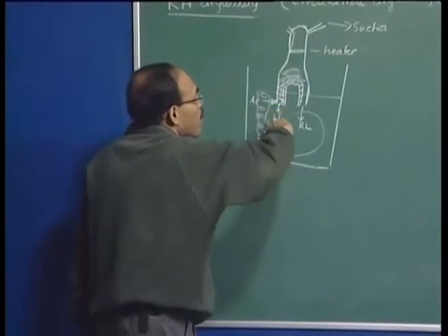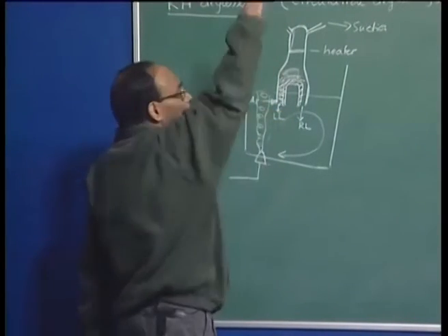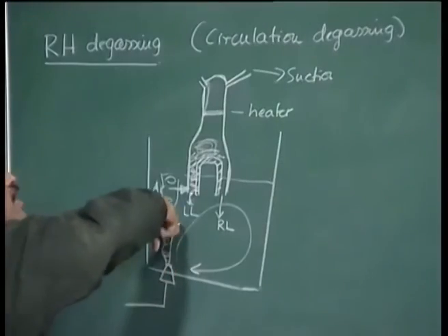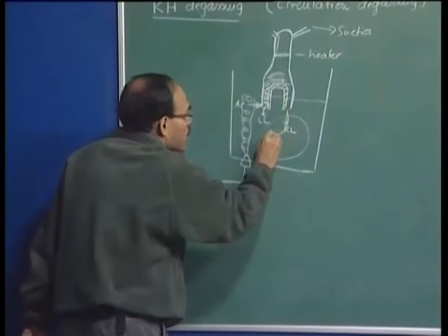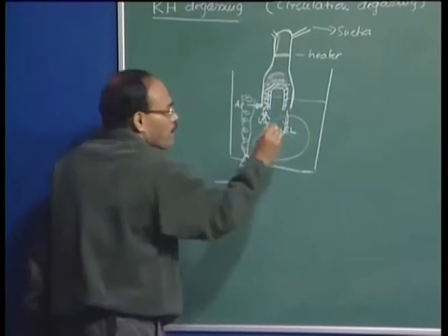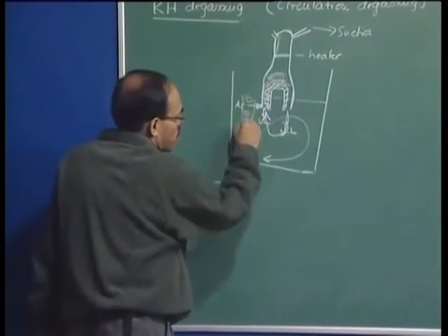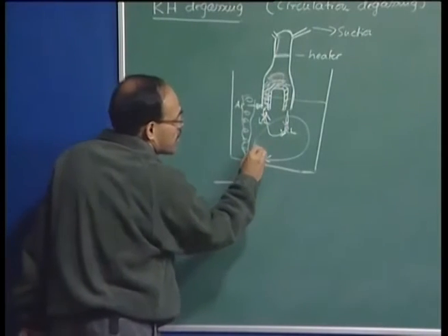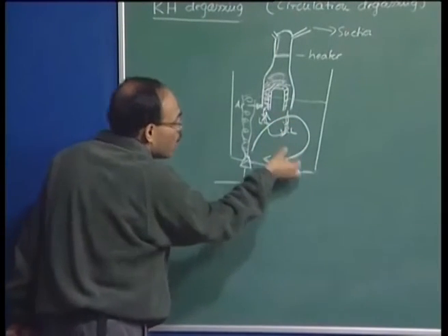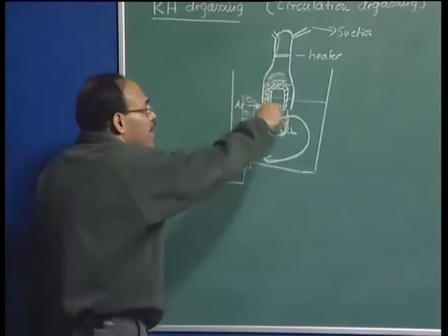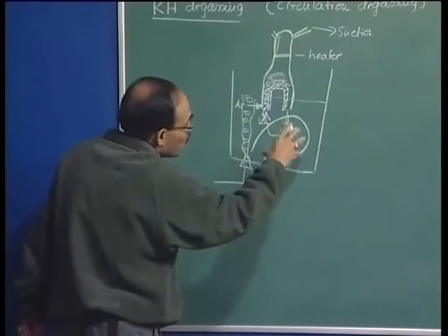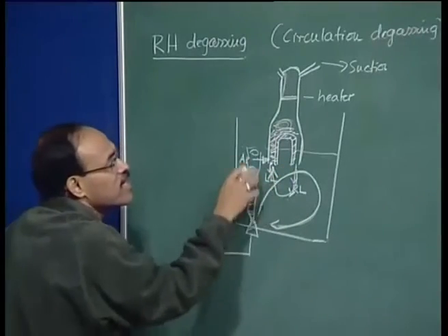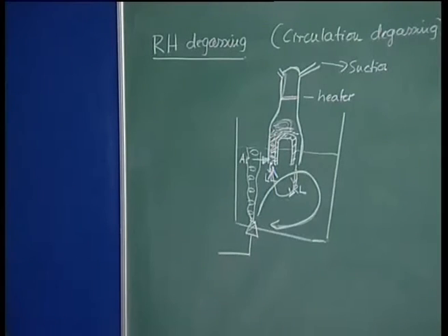So, there is going to be a lot of molten material drawn into the upward leg, and as the material is drawn into the upward leg, from somewhere the material has to come, and as a result some circulation is going to be established. This argon gas injected through the porous plug is now going to bring more and more fresh material into the leg, and as a result the circulation established here is going to expose all the material contained in this system under vacuum, and the material will be effectively degassed.